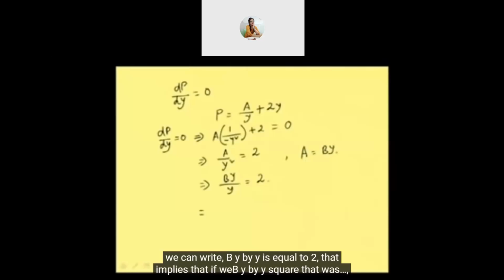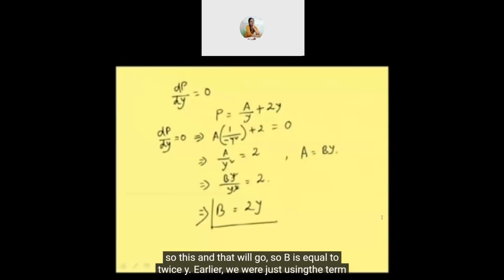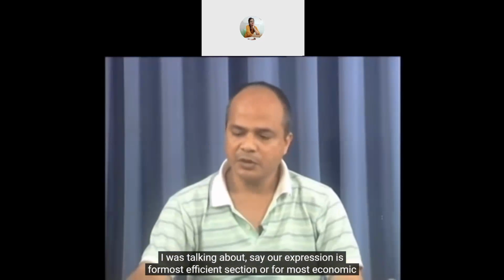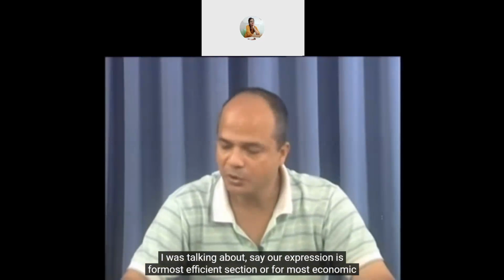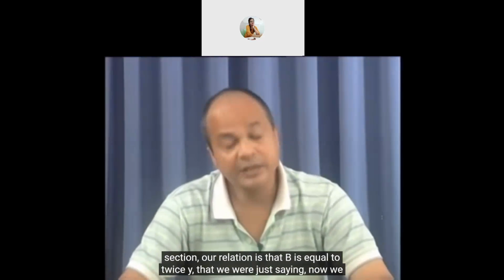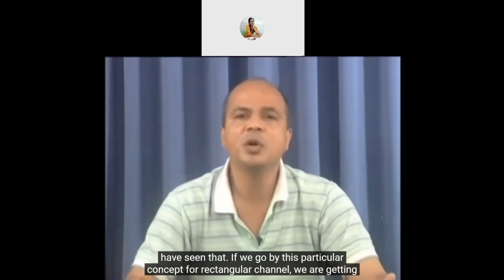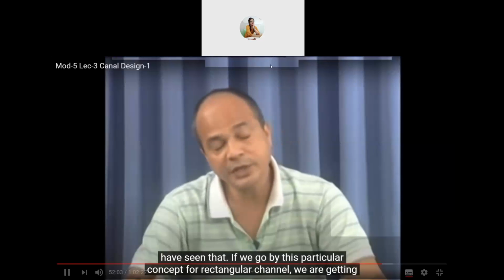So this and that will go, so B is equal to twice Y. Earlier we were just saying that for the most efficient section, or most economic section, our relation is that B is equal to twice Y. Now we have seen that if we go by this particular concept for a rectangular channel, we are getting that B is equal to twice Y.